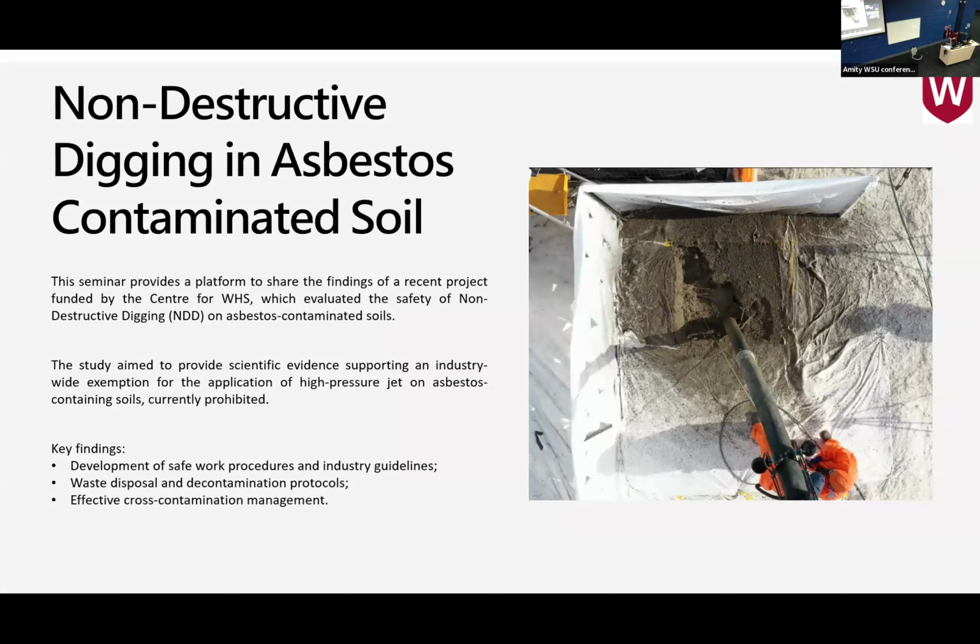There are different techniques for digging, and recently non-destructive digging, where rather than using physical force, you use a high pressure jet, it can be air or water, to break down the soil, and then you suck the slurry in. It's brilliant. It's easy to control. You can dig everywhere you like with high precision, specifically if you have underground utility. It's an amazing construction excavation technique.